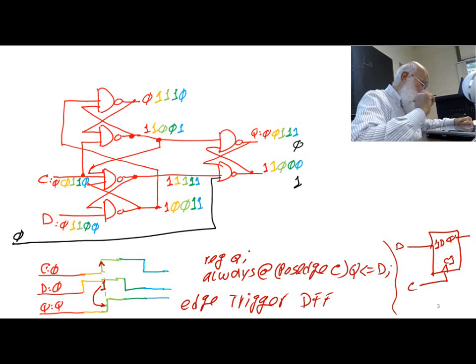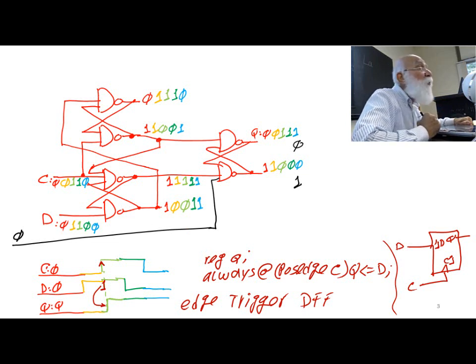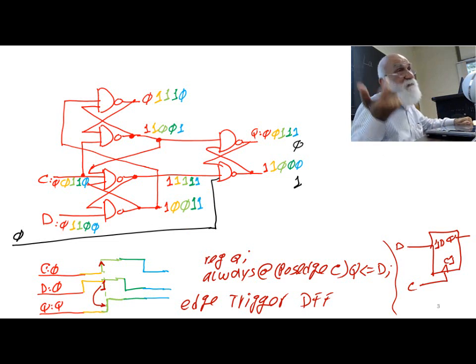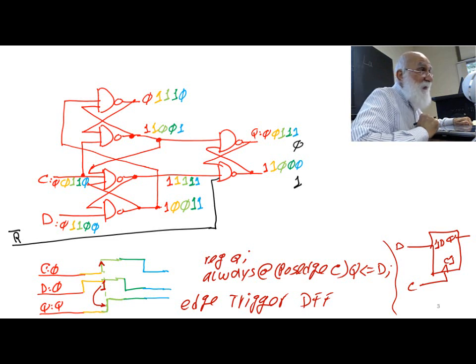Okay, so I just added the signal to the circuit that forces my output to reset to 0. But that happens when it is 0, so I call this one active low reset. It is an active low reset. But the problem with this is it's really not permanent.